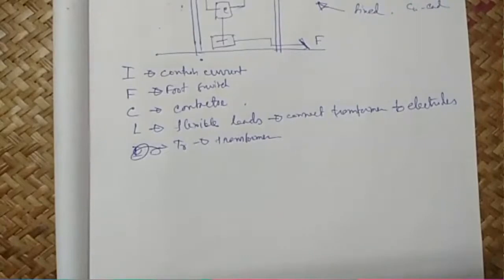Or you just draw the diagram, because the diagram is everything. Now, for higher productivity or higher duty cycle, you need to provide cooling water through the electrodes. Otherwise, the electrodes will heat up, and your production will face less time, less manufacturing lead time. So the variables here